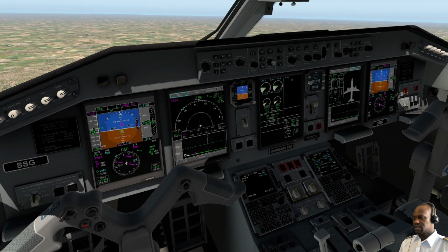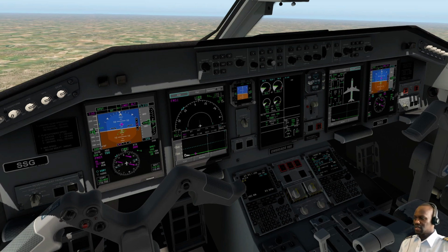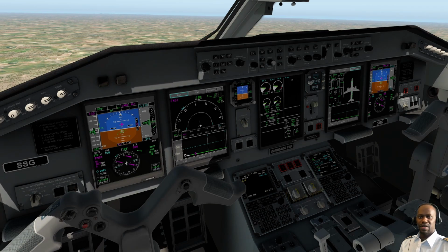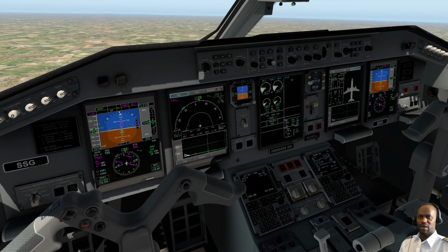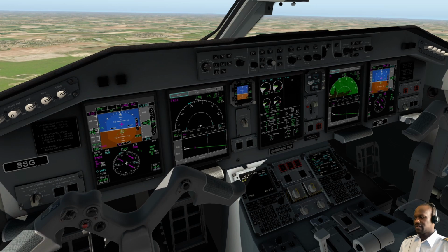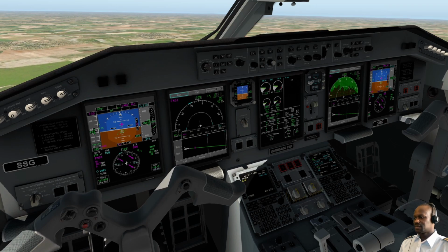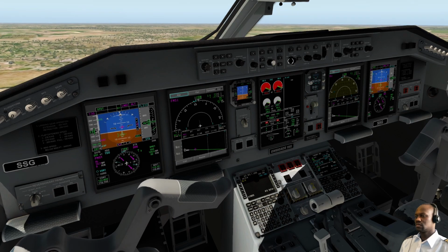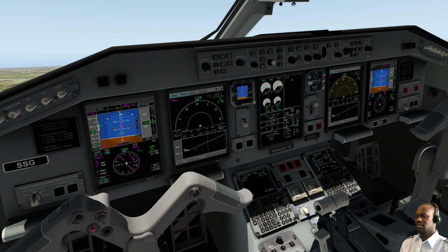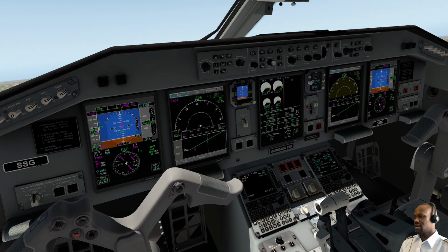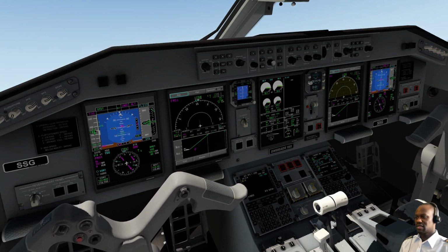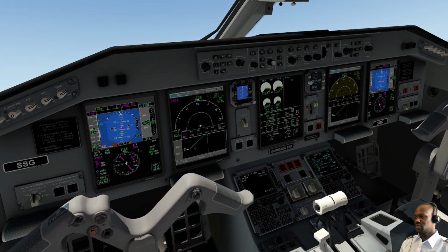Flight level 080, we just crossed the transition level, so at this point we should have set our QNH, a local QNH. Since we didn't speak to ATC, then we don't have the QNH as well. The radar altimeter is alive, about 1,000 feet to the ground. Sink rate, too low. I'm going to recover this aircraft, because I don't like seeing aircraft that are crashing. That was an EGPWS: set max thrust and pitch up to 20 degrees.